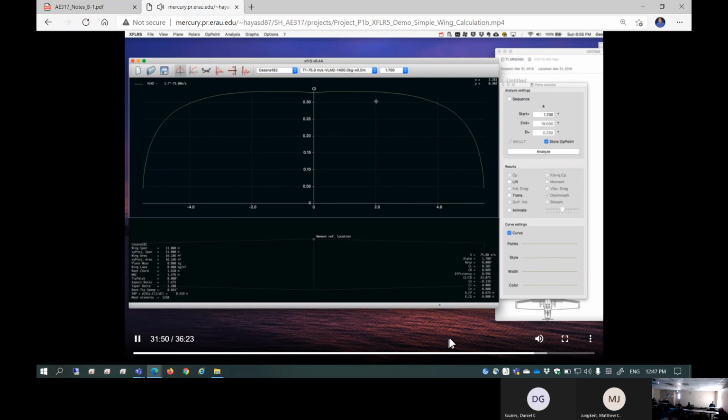So the whole wing coefficient must average to this right here, this dashed line or dotted line. So the outboard sections are below, the inboard sections are above in terms of the lift coefficient. So we have higher loading on the inboard, going to 0 at the tips, but a fairly elliptical looking distribution. This is a lift coefficient, but an elliptical looking distribution.